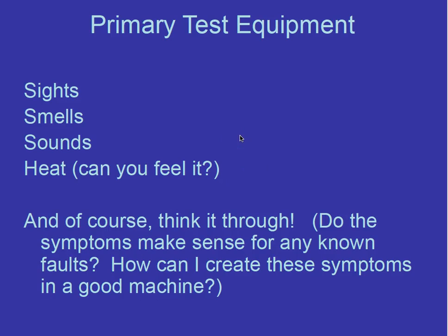Primary test equipments include sight, smells, sounds, heat. So look for these signs and see. So these steps also involve getting physical contact with the circuit. So it is better to first remove the power supply to the circuit and then wait for some time to discharge the current in some components, so that you can hold it without fear. And if you don't go with removing the power supply first,